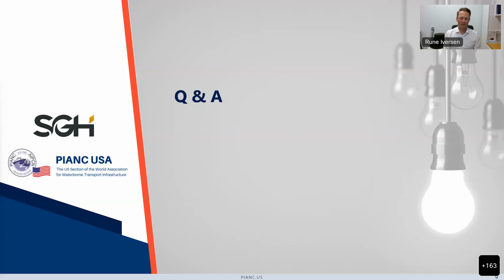I'm relating this directly to what's happening in the United States. For any load factors applied to berthing forces, it's important that you know what reaction force from a fender you should apply that load factor to. There are going to be clarifications coming on that in the future on how to actually do this. Right now, the guidelines aren't very clear on that, but that's something being worked on now, to avoid over-designing the supporting structure.